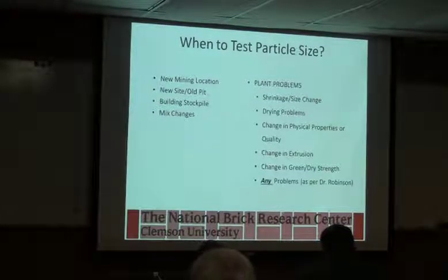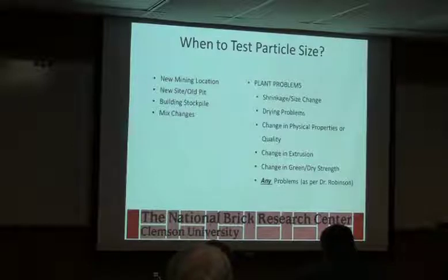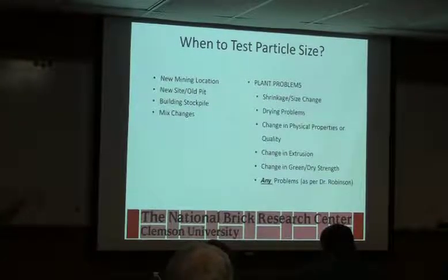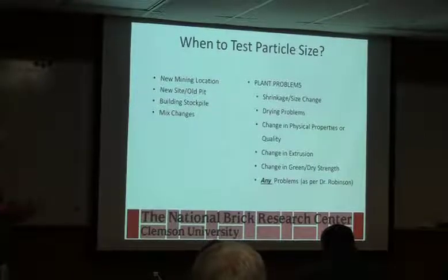When to test particle size. New mining locations, new site or pit, when you're building a stockpile is a good place to look at it. And then anytime you're doing a mix change is a good place to look at it. Again, the more data you have, granted, it takes time to collect the data, but you'll just smile when you do run into a problem, because then it gives you something to look at rather than just guessing.